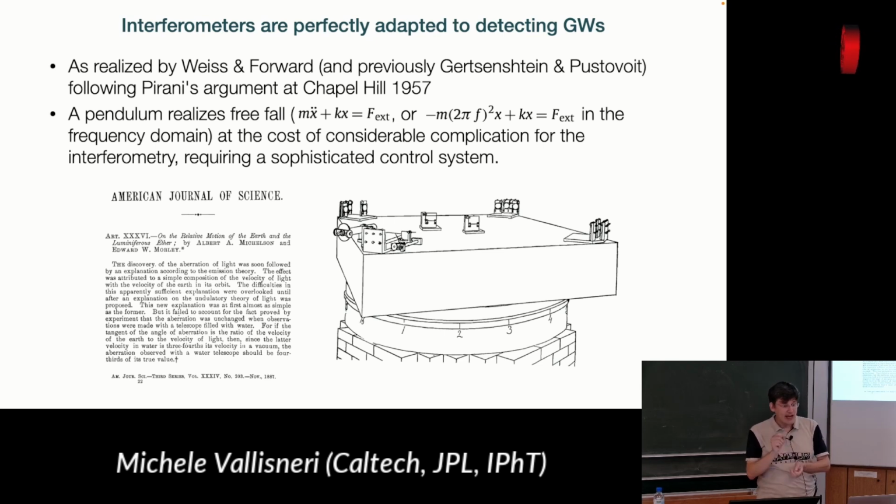So if you add an external force that is at much higher frequency than the pendulum itself, the pendulum doesn't feel it. So it's superposed onto the motion of the pendulum. Another way of saying it is that the swinging mass behaves as a freely falling mass at frequencies that are removed from the natural frequency of the pendulum. Does it make sense?